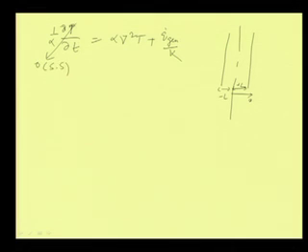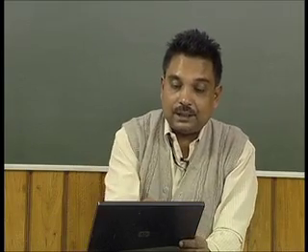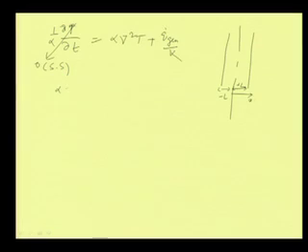But here I am trying to see what is going to happen if there is heat generation in this metal body. Under that situation, we will say that grad square T plus q dot gen by k equals 0.